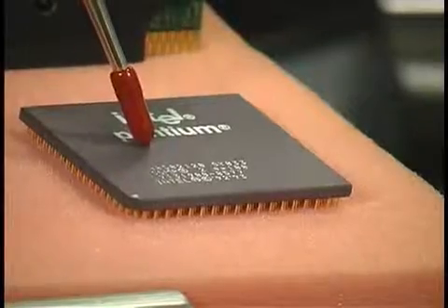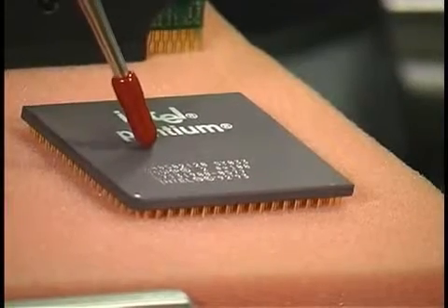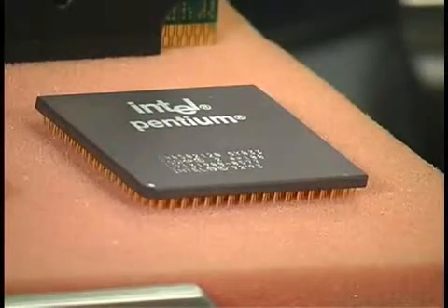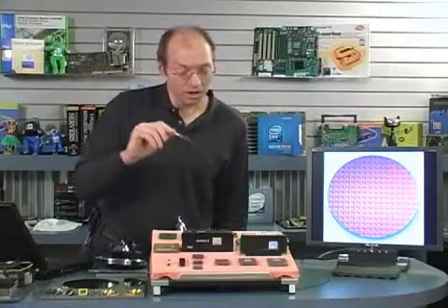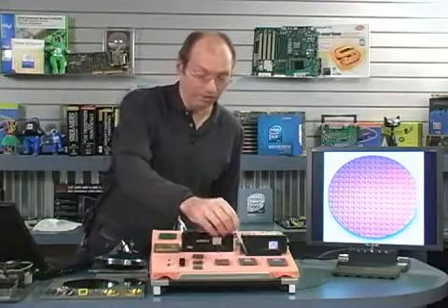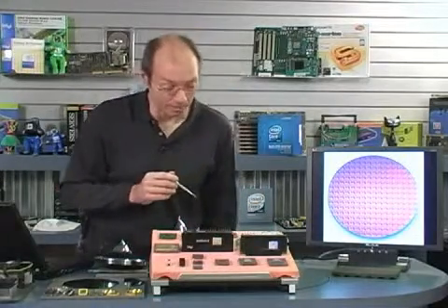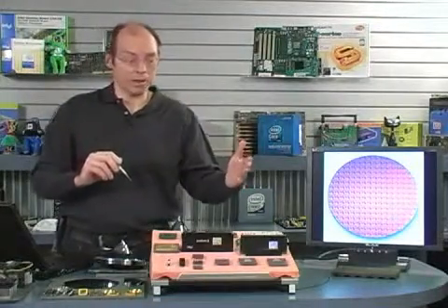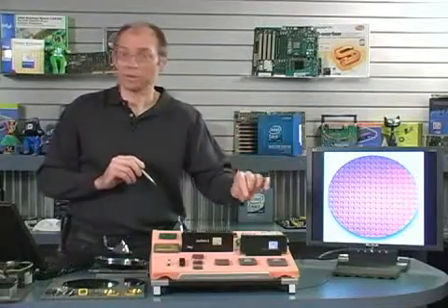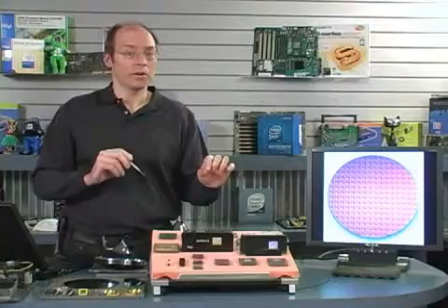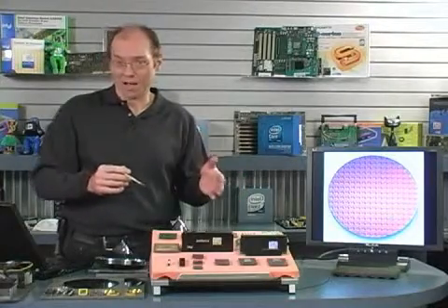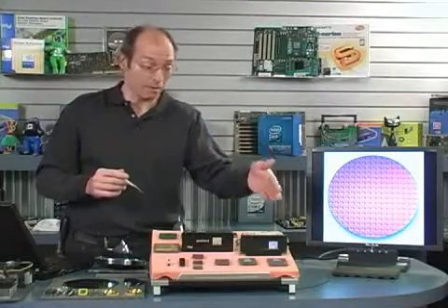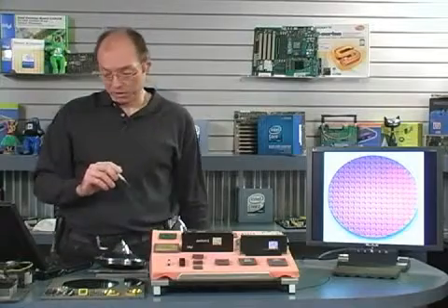Then we have here the 586 processor, which really wasn't called a 586, it was called a Pentium. The first Pentium came out in 1993 and had just over 3 million transistors on it. The Pentium was also, like the 386 and 486 before it, a 32-bit processor. Now, that concept of cache I was telling you about, yes, the Pentium also had the cache built into it, but this was what we call level 1 cache. During those times, level 2 cache was still found on the motherboard, and therefore it ran at slower motherboard level speeds instead of higher or faster processor level speeds. So the next processor would change this radically.